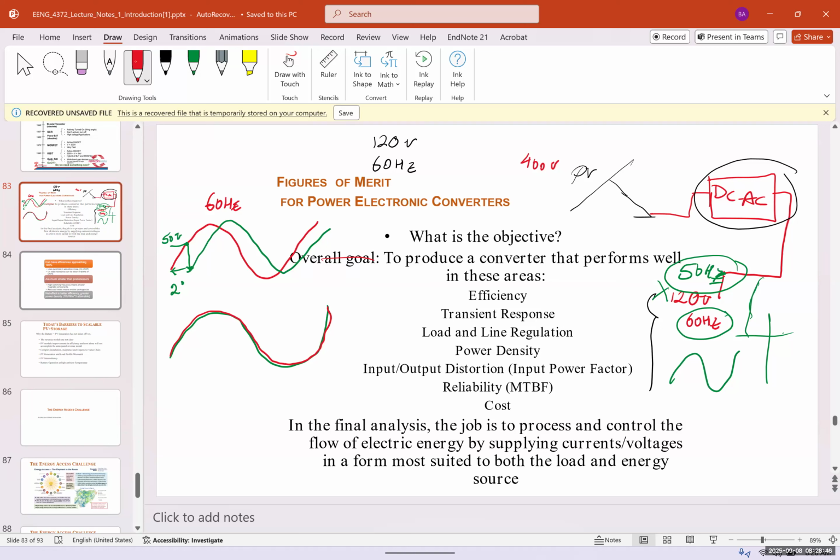And we use a thing called a synchronizer. Have you seen them if you've been to a power plant? There's a big dial that shows when the frequency of the power plant matches the frequency of the grid. You have to perfectly match that. If there's even a little bit of misalignment, like 2-3 degrees, it's going to damage both the power plant, and that's a 300 megawatt power plant, and also the grid. It's going to create a lot of problems.